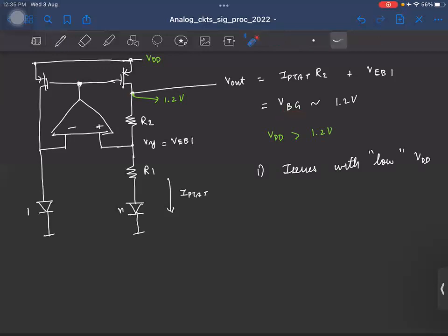And another thing is sometimes you may not exactly want to generate this bandgap voltage. We might want to generate, say, a fraction of this. So basically, this will not be exactly 5 volt. So what we'll do is we'll generate, let's say, 1 volt or 1.2 volt VDD from some other circuit. And how we'll generate it, that is also based on this bandgap. I mean, we'll discuss it probably later. Now, assume that we have the supply of, say, 1.5 volt or whatever. We have to generate this 1.2 volt bandgap voltage. We need a higher VDD, right? So let's say we have it for now.